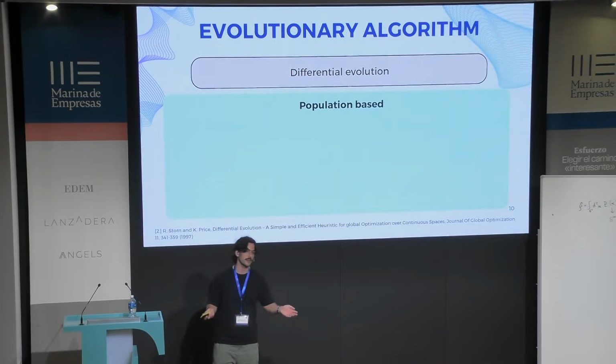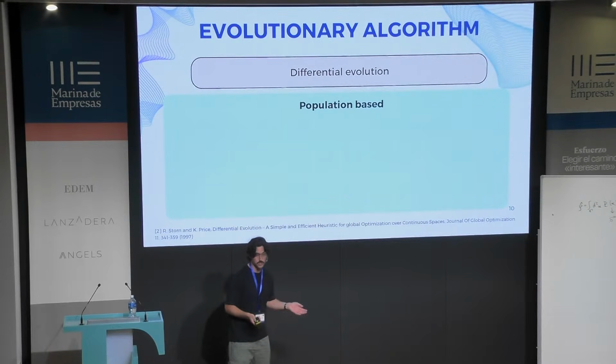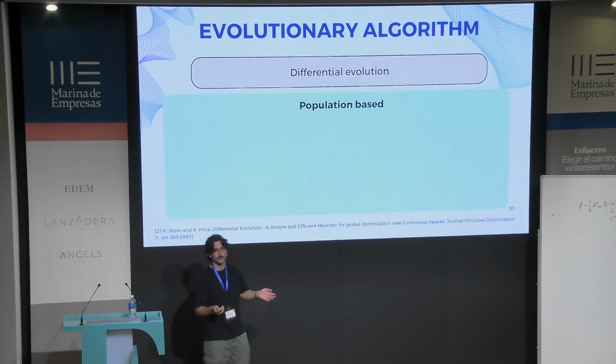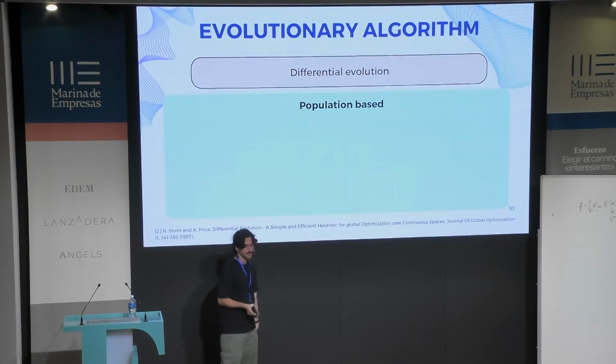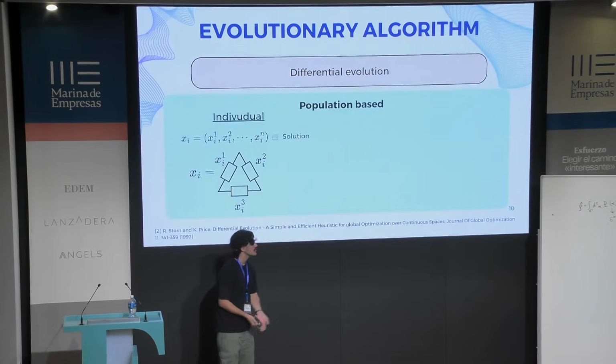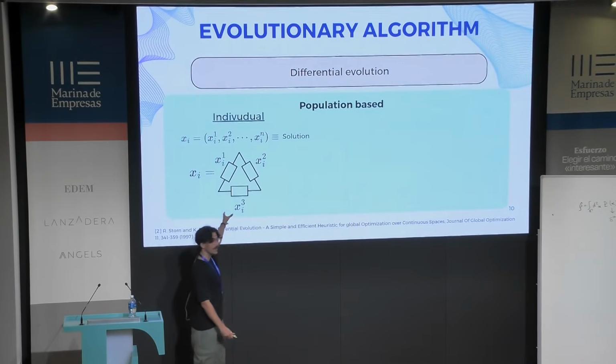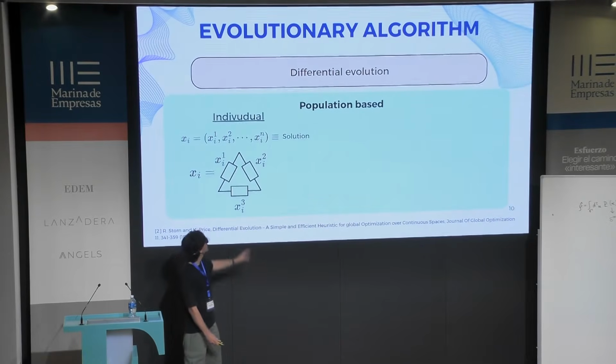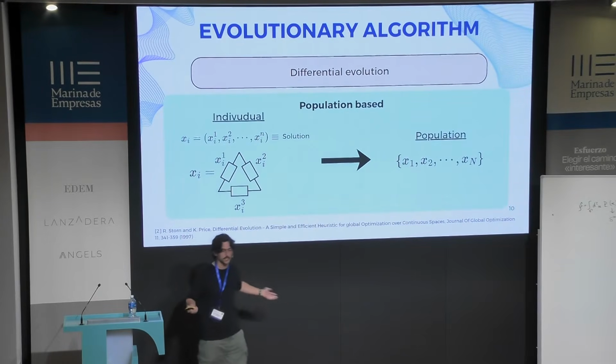We are going to take an evolutionary approach to this problem. The algorithm is called differential evolution, which is a type of global optimizer, basically, and it's a population-based optimizer. So what does that mean, right? We will have our circuit with the parameters of our components, and we are going to map those components into a vector, and that vector is the so-called individual or solution, and then we will make a bunch of them, and that will be our population, right?